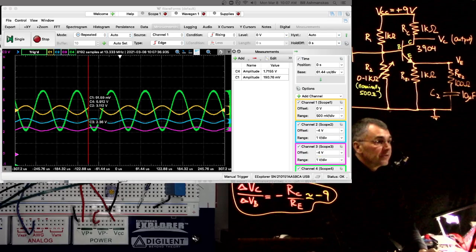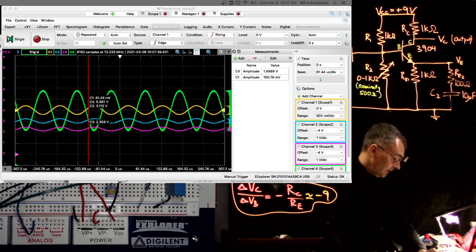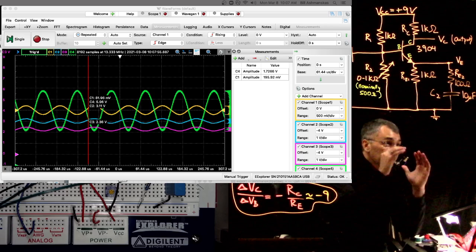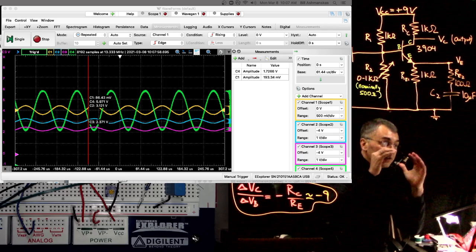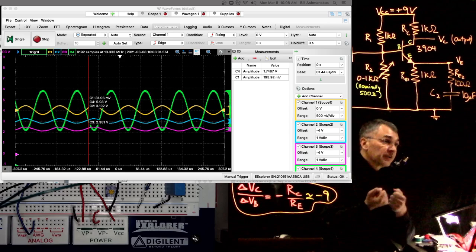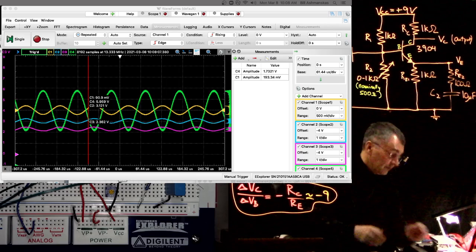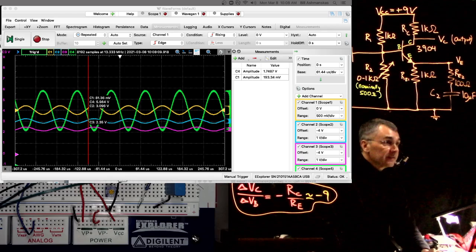And I miraculously fixed my fuzz problem by making the wire that I'm using for scope channel 1 shorter. So I just picked up the shortest wire that would make the desired connection for scope channel 1. And miraculously the fuzz is gone. So sometimes a long wire, especially a long wire that encloses a big loop area, can get a time-varying magnetic flux that induces an EMF in that wire, and you can magnetically pick up a signal that couples into your circuit and parasitically oscillates.